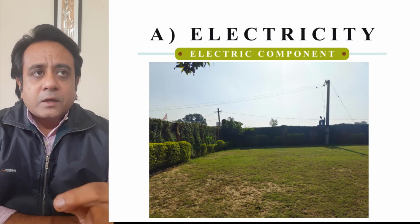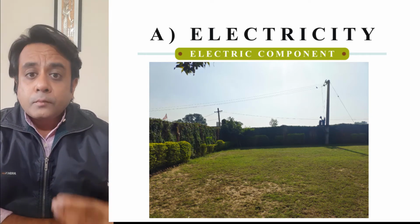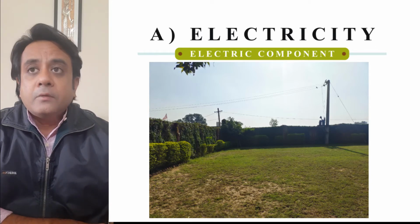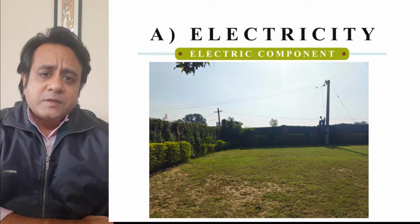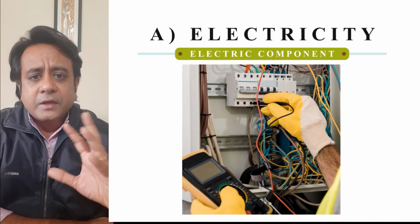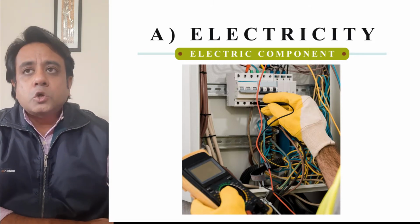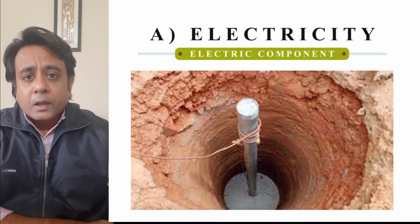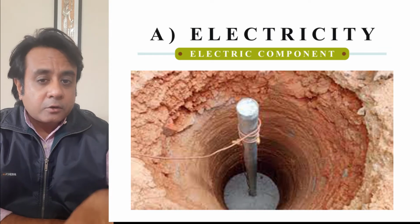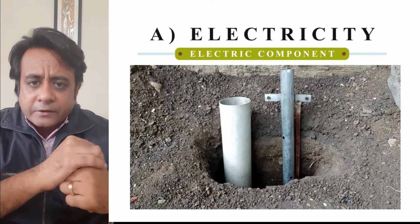Once I am clear with that, I need to understand if there is any transformer, any distribution box, any core cabling that is happening, where my meter is going to get installed, and where my MCB is going to get installed. Coming to the MCB is a little early at the site stage, but if you have that at the back of your mind, it gives you a clear picture of how the circulation of the electric cabling and other things can happen. And yes, it's very important to know where you would be doing the earthing, because it's a pit which has to be dug, and then the copper plate and everything goes down. So these are the things you need to understand in terms of the electric services.